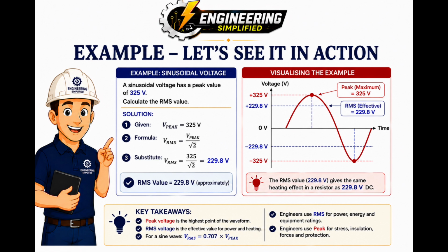In our first example, we have a sinusoidal voltage with a peak value of 325 volts. We want to calculate the RMS voltage. We use the formula RMS equals peak divided by the square root of 2. Substituting our value gives RMS equals 325 divided by the square root of 2. The square root of 2 is approximately 1.414, so 325 divided by 1.414 gives approximately 229.8 volts. Therefore, a sinusoidal waveform with a peak voltage of 325 volts has an RMS voltage of approximately 230 volts.